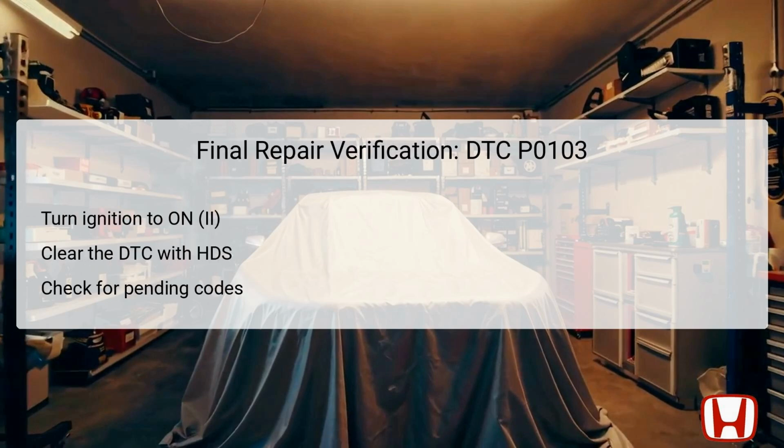In the final repair verification step, turn the ignition switch back to the on second position. This reactivates all electrical systems and allows for final diagnostics. Use the Honda Diagnostic System, HDS, to clear any diagnostic trouble codes that have been previously stored. This essential step refreshes the vehicle system and helps ensure that old codes do not interfere with new testing.